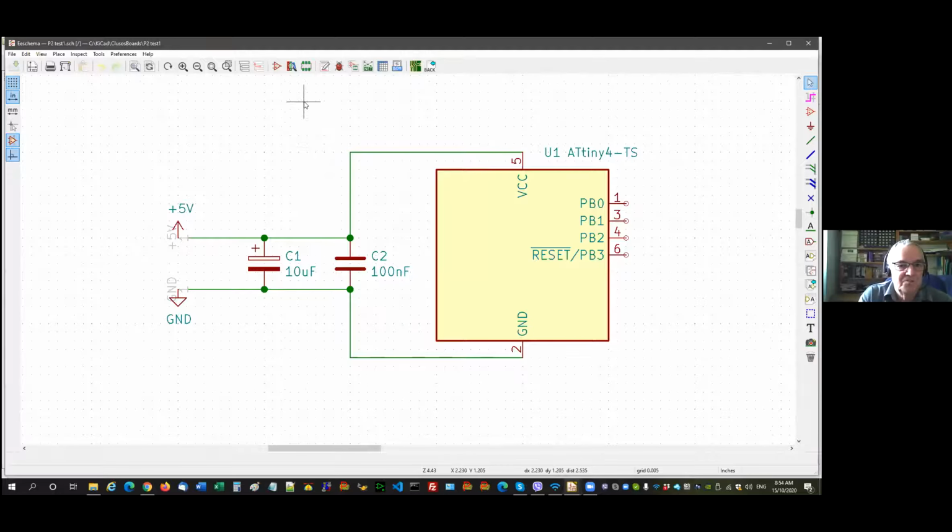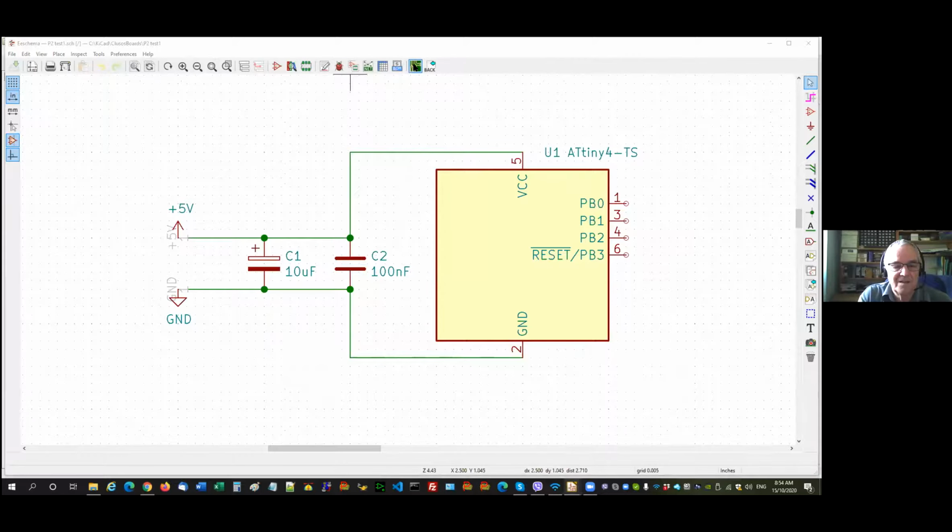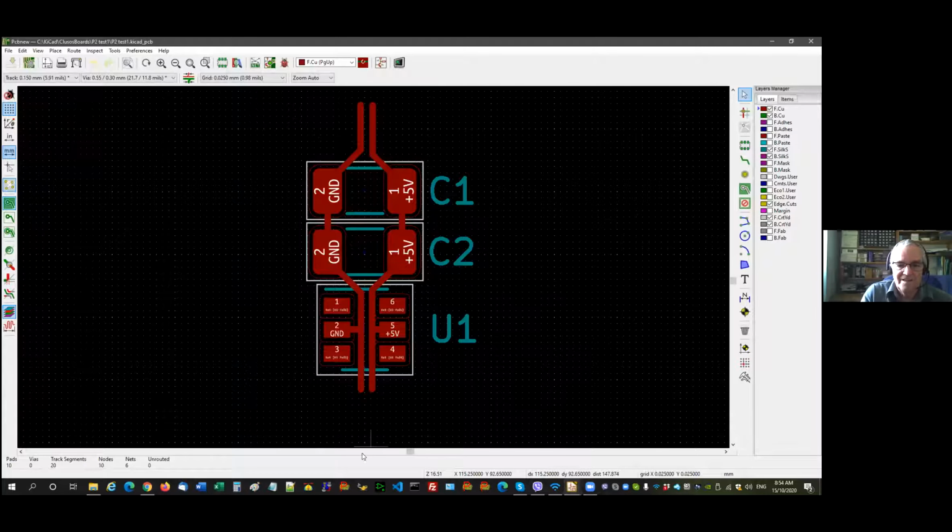Now, to show how that layers up, here's what you really should be doing. You really should be coming through your pad. That forces this capacitor to do its job the best as it possibly can. If I was to bring that down there and just drop that across there, that capacitor doesn't quite do the same job as it does by coming through the capacitor. And that's what I've tried in all my designs.